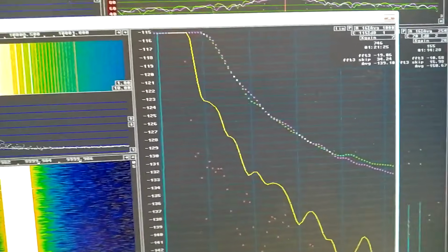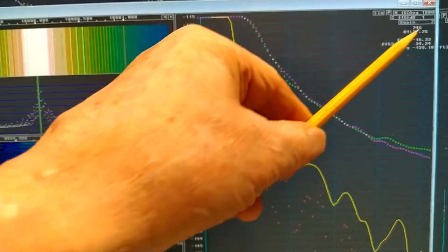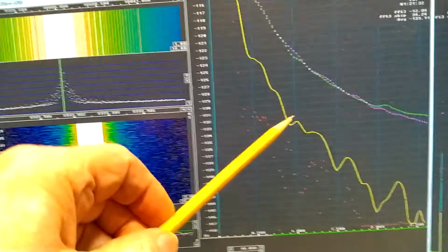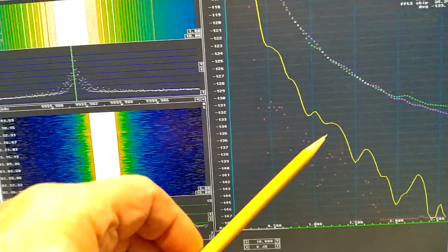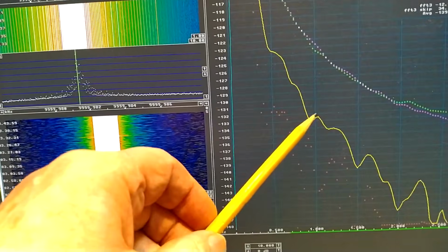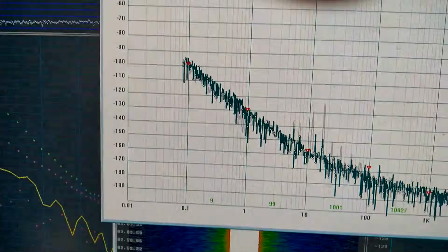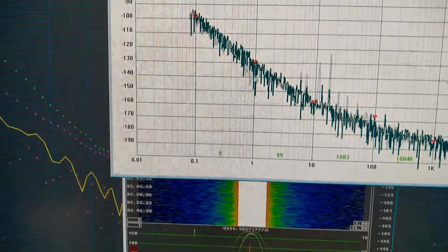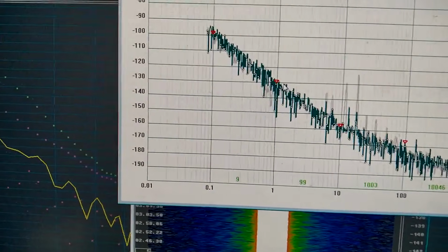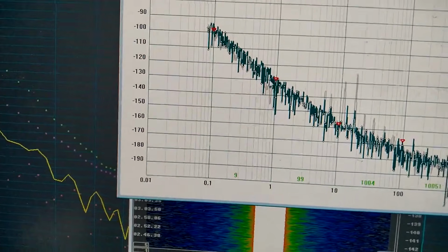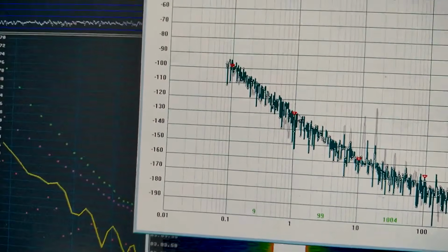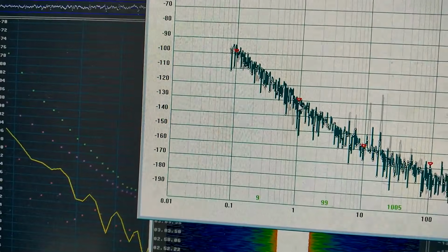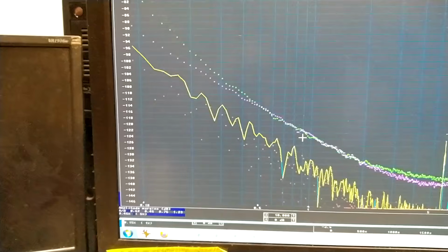It is obtained, this result, after 1 hour and 20 minutes. And statistics is not good enough to get the decimal on the phase noise. About 132. The result in the PN 2060 is a little better than minus 130, but there are circles around here, so when it has converged it will be a little bit better than this, maybe 132 or 133 even.